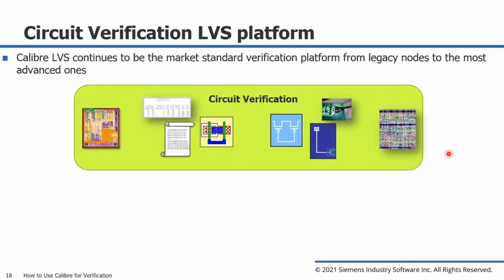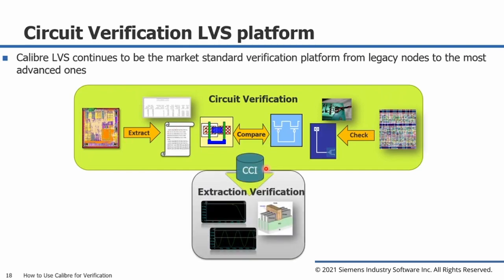Now we'll move on to the circuit verification LVS platform. Calibre LVS continues to be the market standard verification platform from legacy nodes to the most advanced nodes. Here you can see the circuit verification, where you have extraction from layout, or you design your netlist, and from the source netlist you can compare it and do LVS.